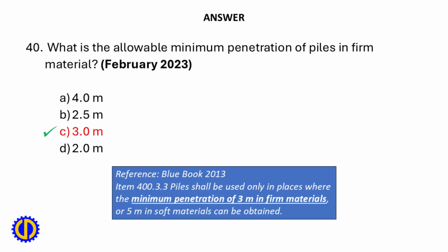C. 3.0 meters. Reference: Blue Book 2013, Item 400.3.3. Piles shall be used only in places where the minimum penetration of 3 meters in firm materials, or 5 meters in soft materials, can be obtained.